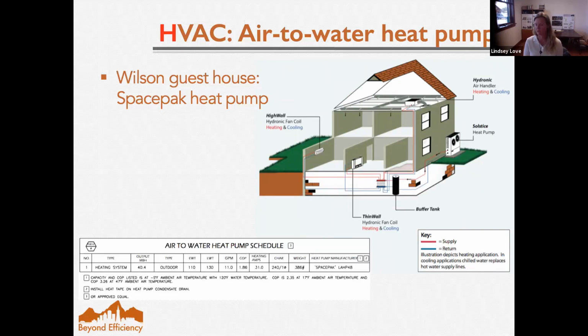Yep. But some of these heat pumps go up to, say, 3, 4, 5 COP. The Sanden, I think its COP is like 4.5 at around 40 degrees. So it's pretty amazing. And we have done a number of combi space heating and domestic hot water systems with Sanden.